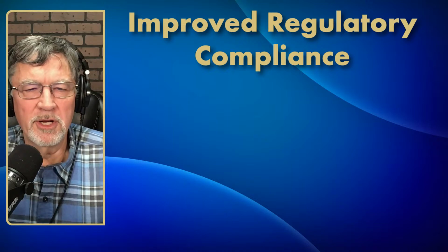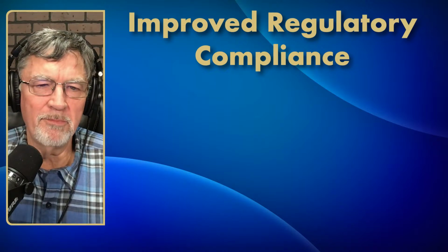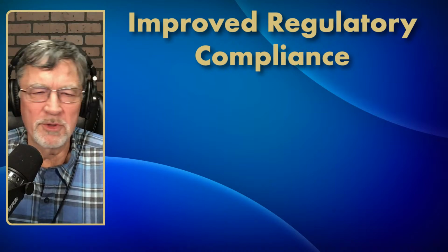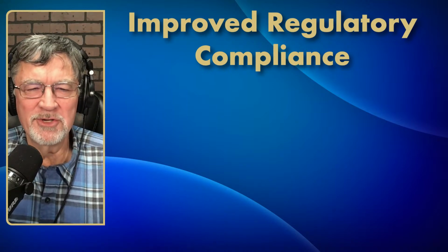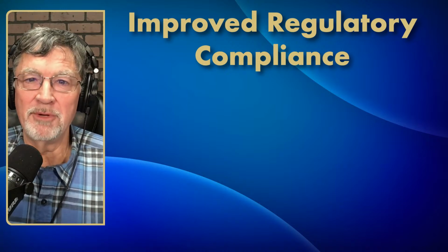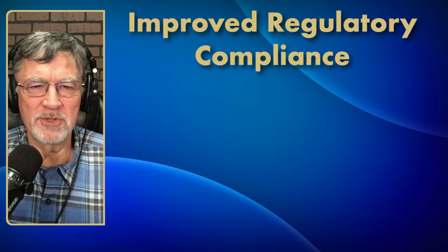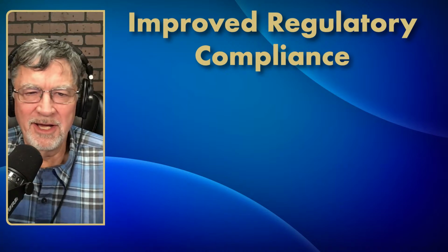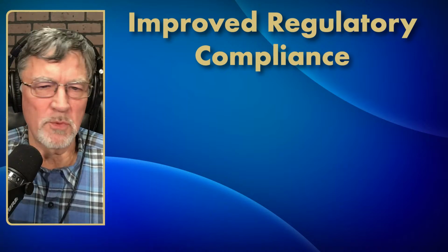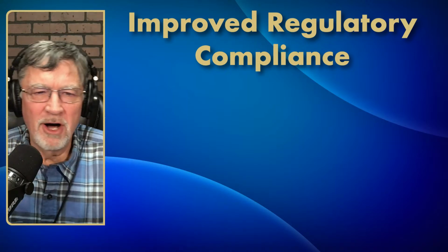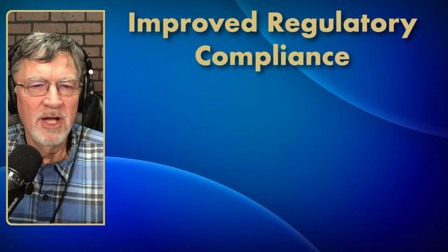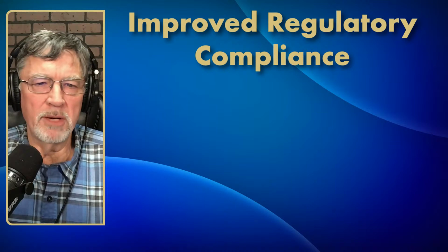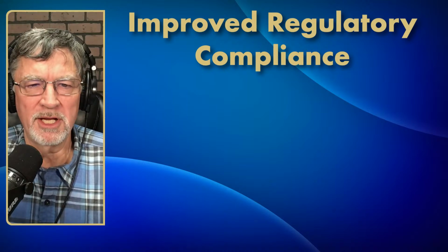All right, improved regulatory compliance, our final component here, but certainly not the least important, is staying up with the regulatory compliance. And the regulators do not look on you kindly if you have common failures. You're getting boil water notices all the time because you had a leak or some kind of surface water intrusion into your well that the coliform's kicked up and now you got a boil water order, or just constant failures and your chlorinators going out, not operating properly, so your chlorine residuals are not where they need to be.